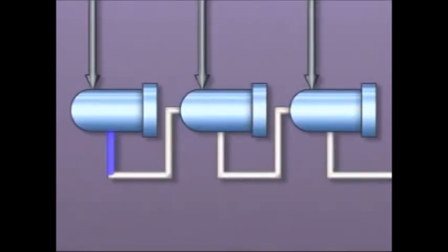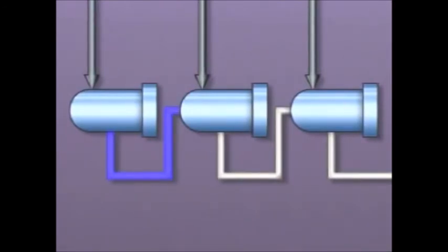That is, the drips flow through the normal drain line from one heater into the shell side of the next heater in the train. This heater has a lower temperature and a lower shell side pressure than the first heater has. The drips flash to steam because of the lower pressure within the heater's shell. The drips also mix with the extraction steam that's already in the shell. Thus, the drips are another source of heat to be transferred to the feed water in the tube side of the heater.